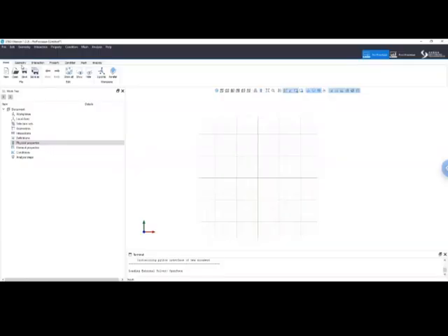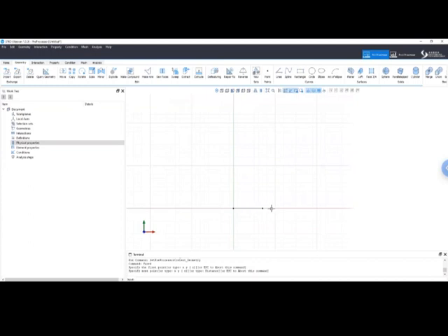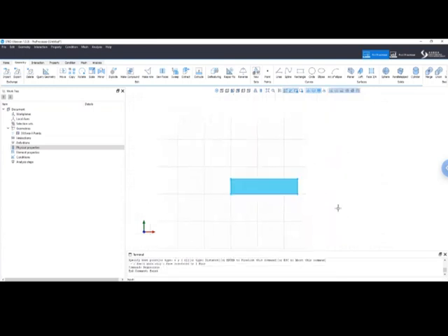So let's start modeling a simple brick. In this case, we are going to stay in the XY plane, because every time you do a 2D analysis, you need to stay in the XY plane. Otherwise, OpenSees will complain about the orientation. So we can start with a planar face. So we click this one, and we start from the 0 coordinate. Then we go to the right by 2050. I'm going to type 2050 millimeters on the input bar. Press Enter. And then 55. Then we go back 2050. And we are done with just one of them, okay?